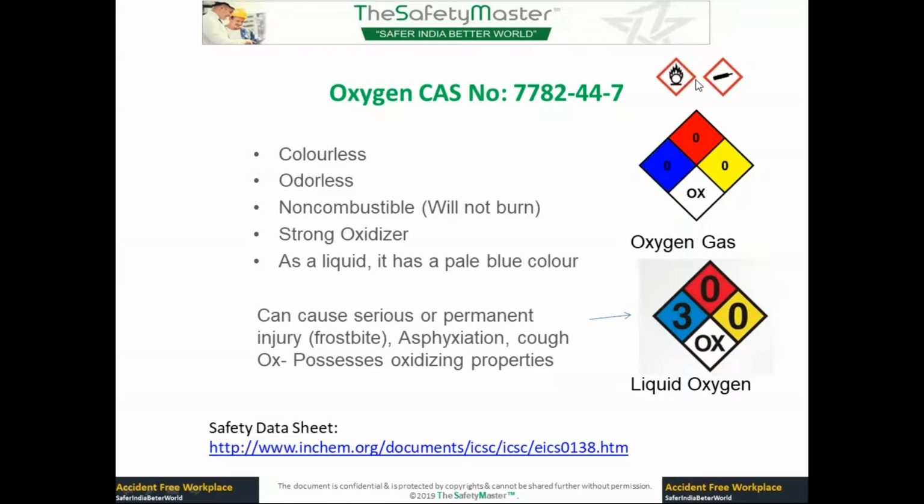Okay, so it means it can catch fire, and the cylinder is pressurized. So this too you'll find when you're handling oxygen cylinders. And in case of liquid oxygen, you'll find 3 here. In case of gas, you don't find it. Gas is never an issue. Okay, but in case of liquid, yes, there is a health hazard. It can cause frostbite, asphyxiation, cough, and it has other oxidizing properties. Okay, so this is one of the major hazards with oxygen.